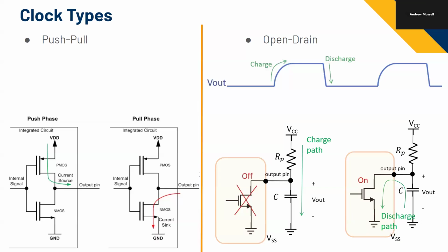You see when the transistor is shorted to ground, we're discharging the capacitor. You have to sink current out of the capacitor to discharge it. But the resistor is still connected to power, so we also have to pull current over that resistor to cause a voltage drop across it. So let's say we eventually discharged and there's no energy in the capacitor.